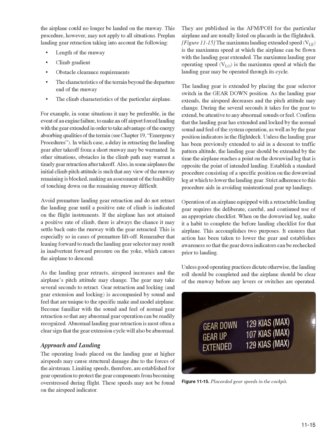Also, in some airplanes the initial climb pitch attitude is such that any view of the runway remaining is blocked, making an assessment of the feasibility of touching down on the remaining runway difficult. Avoid premature landing gear retraction and do not retract the landing gear until a positive rate of climb is indicated on the flight instruments. If the airplane has not attained a positive rate of climb, there is always the chance it may settle back onto the runway with the gear retracted. This is especially so in cases of premature liftoff.